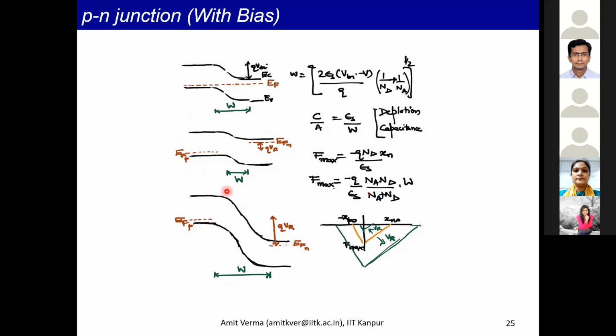On the other hand, in the reverse bias, when you make the barrier very large, you have a lot of electrons here, but then the barrier is so large, they cannot cross it, okay? Because the electrons are distributed in energy. There are not many electrons at these higher energies. So you have very less current. And that is why the rectifying characteristics of a PN junction comes about.